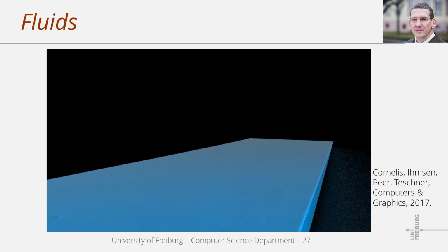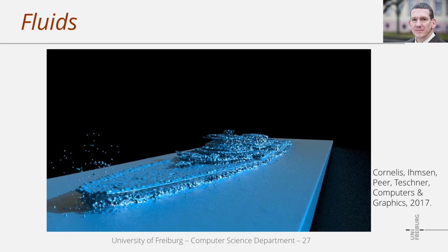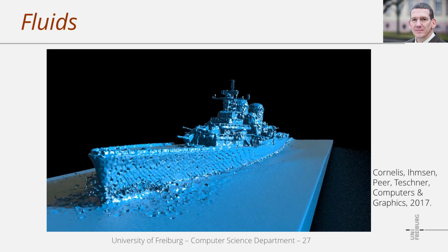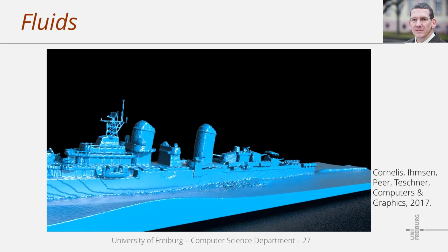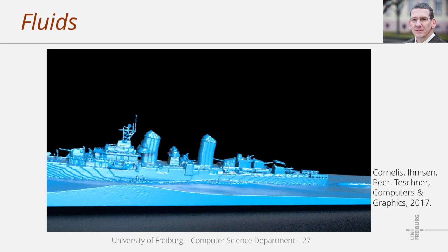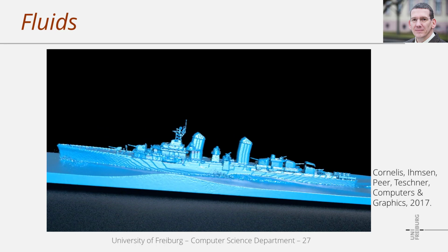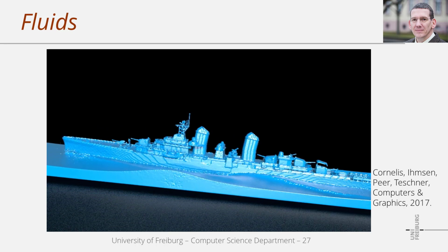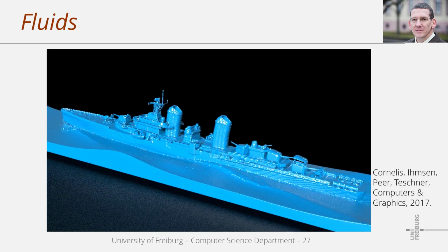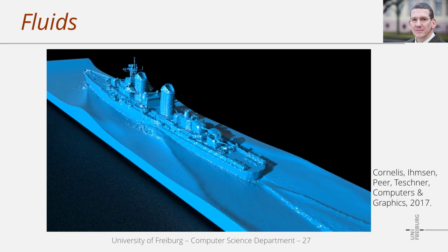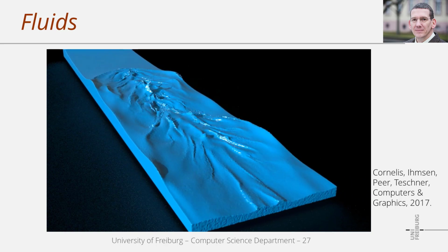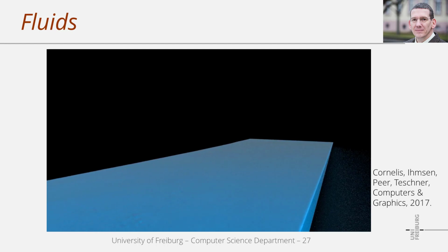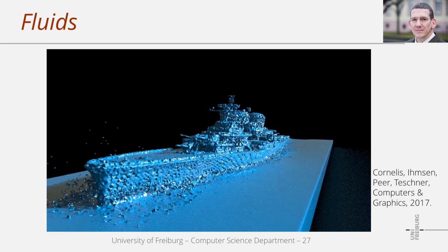With this last fluid video, I'd like to show that our work also addresses artificial visual effects. So here in this approach we can solidify parts of a fluid and we can melt rigid objects back to a fluid. The realization of such effects is actually not too difficult if you have a state-of-the-art SPH fluid solver. The idea is just to change the force computation at particles. If we solidify a particle, we basically stop the computation of fluid forces at a particle, and if we melt a particle, then we start the computation of fluid forces again.